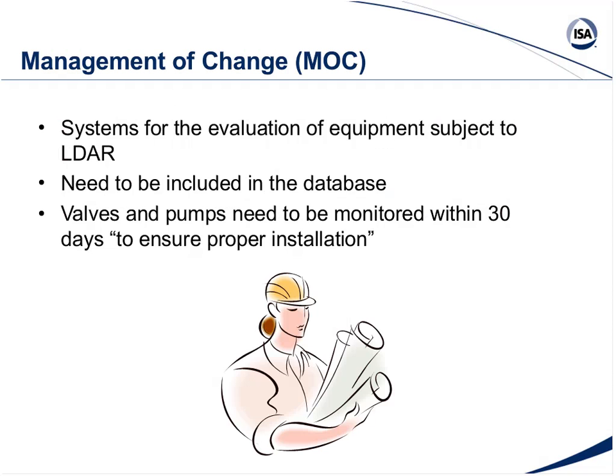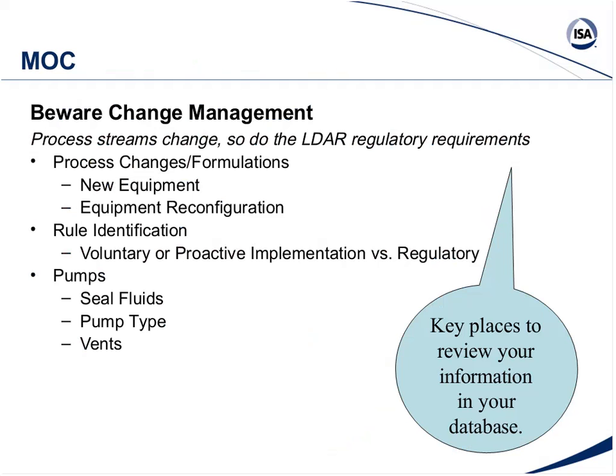Management of change, you've got to watch that, and usually the place now is getting that first initial monitoring event. When did the component come into service? And now there are a lot of things that pumps and valves need to be monitored for to ensure proper installation. So that's another aspect of the rule where things might get fuzzy. So we're getting close to the end here. You want to be aware of your change management, because that's going to be what's going on. You want to make sure you're reviewing the information in your LDAR database to make sure that that's happening and you're getting that change management as well.